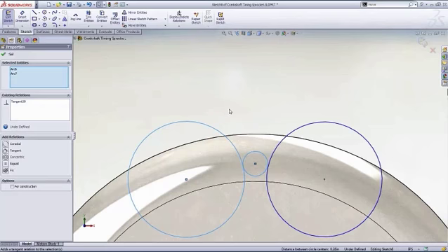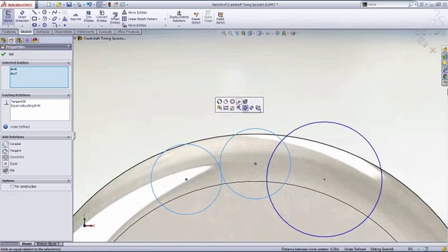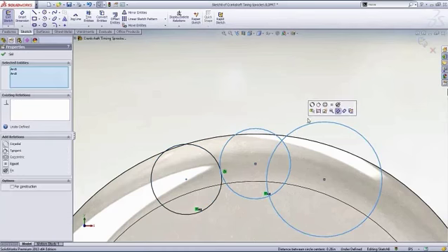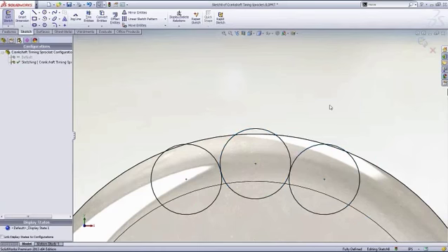All I actually need to do is simply repress the Control key and the pop-up returns. Now I can select equal, and even if I wanted, press Control again and continue adding more relations. This is much faster than reselecting the geometry or moving back and forth from the property manager to the graphics area. Now that we've looked at sketch relationships, I want to take a moment to look at Power Trim.